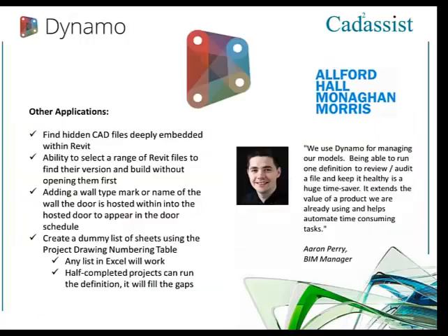Other ways that they save time, particularly from a model management standpoint, they use Dynamo for doing things like finding hidden CAD files that are lost in a Revit model, or being able to select a range of Revit files to find their version and build without opening each file individually, or creating a dummy list of sheets using the project drawing numbering table.